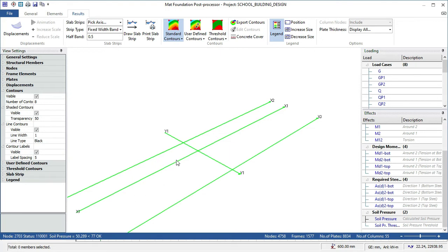Don't, I say again, don't click anywhere, because once you click anywhere, it will make your system slow or hang, and most times the software can just shut down. And if the software shuts down at this very stage, everything you have done is lost, because we have not saved anything, and you cannot save in this place. If you try to save here, it will not save the main Prota software model. So you can see that we are now on strip 1.